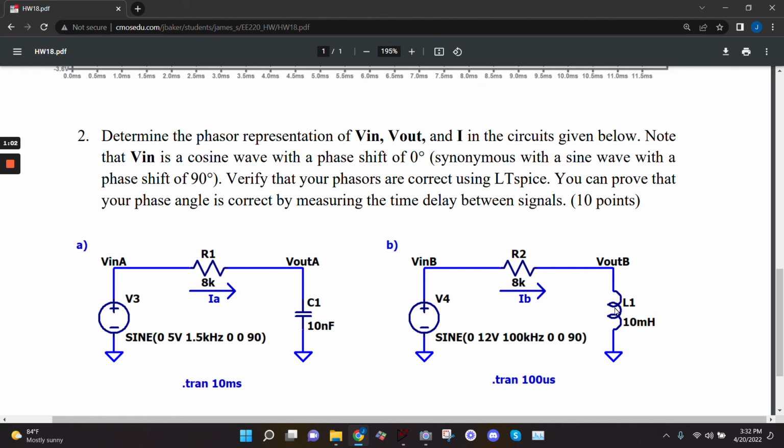It makes sense to me that it depends on the speed, because these devices have to take some time to charge and discharge. So if you have a much larger capacitor, it takes a lot longer to charge. And if you put a larger capacitance here, that would also give me a smaller impedance. At DC, it's not really resisting the flow because nothing's going in and nothing's going out. It's not charging or discharging at all. It's basically going to act like a short. But yeah, it's too complicated for me to know for sure. It's not too complicated for someone to know for sure, but it's too complicated for me. I'm sure Dr. Baker could answer that.